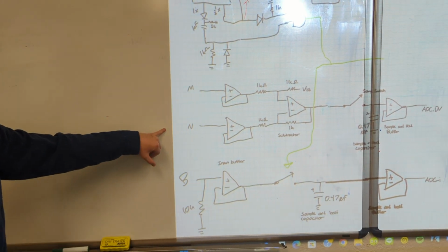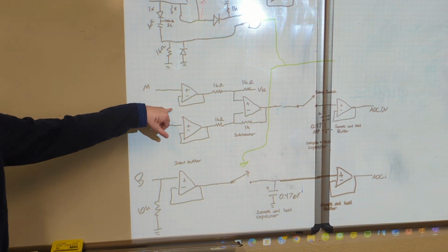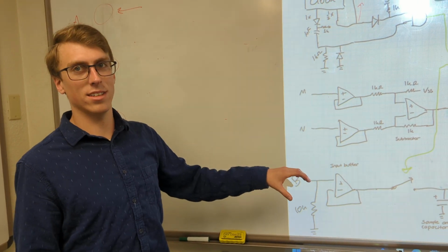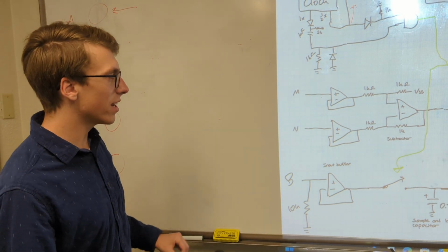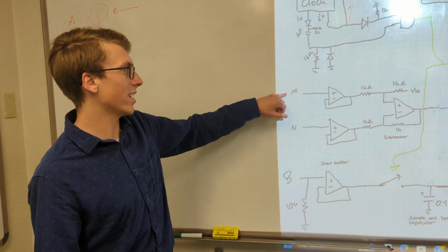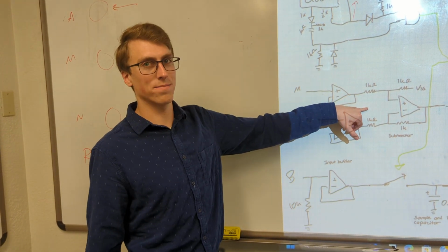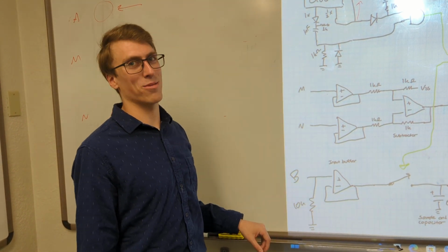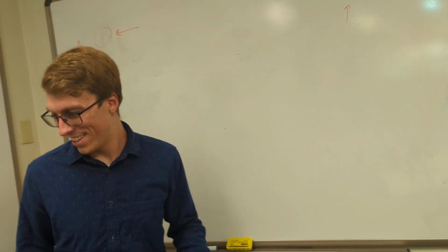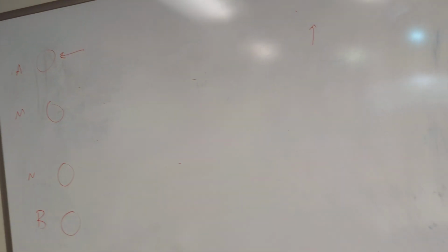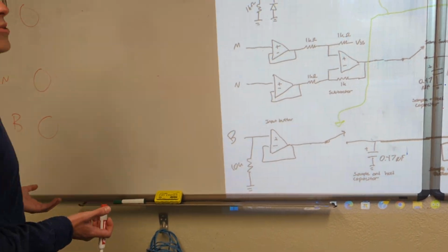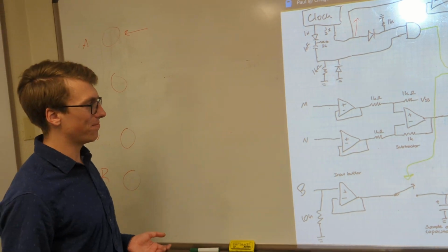Every single input has a unity gain amplifier. What purpose does this serve? This buffers the high impedance from the low impedance. Now, if I were to directly connect this electrode to our voltage comparator, this will draw current from our solution and therefore affect our measurement. As the solution that we're trying to measure has very high impedance, any change in current is going to enact a dramatic change in voltage, which we don't want.